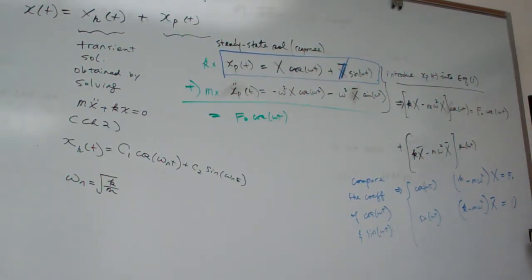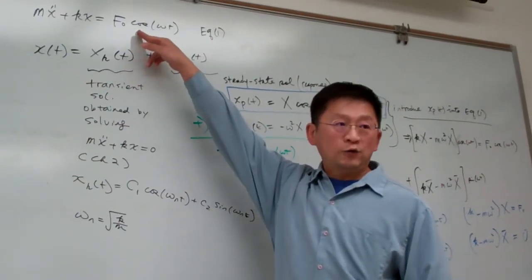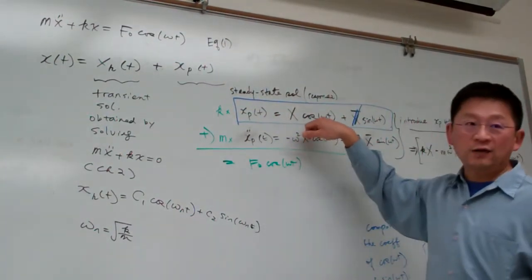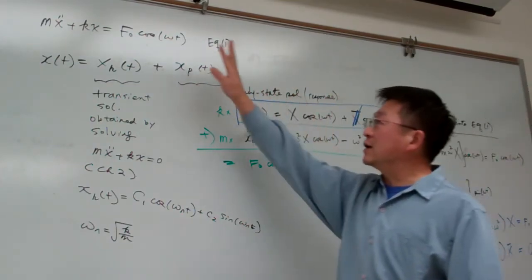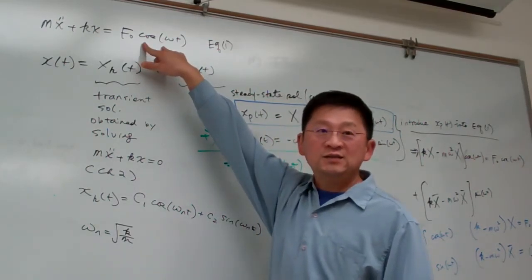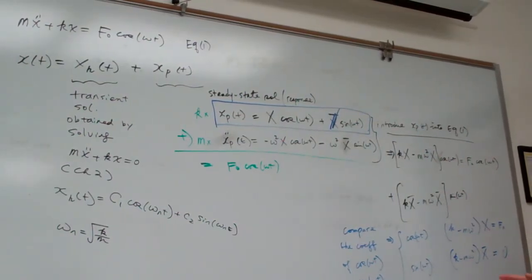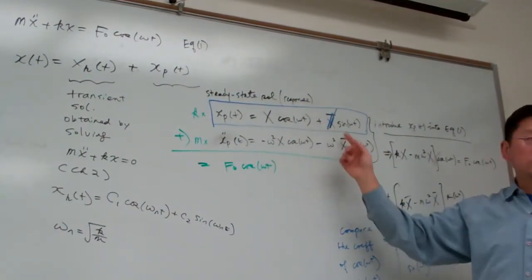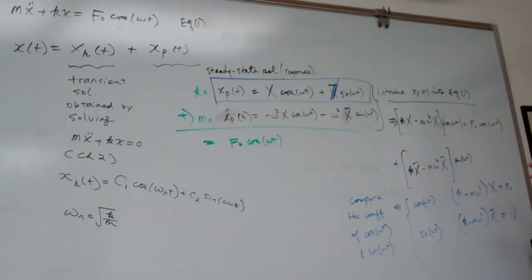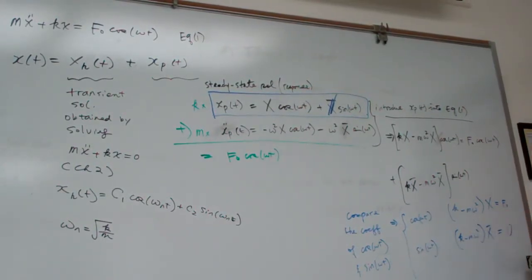So for undamped systems, if the force excitation is in cosine, and here listen carefully, then you simply assume the cosine form only. On the other side, for undamped vibrations, if that force is sine, then you simply assume sine. But generally, if you use a combination of sine and cosine together, it won't hurt. It just gives you a little more rigorous, time-consuming solution process, but eventually you will get it.